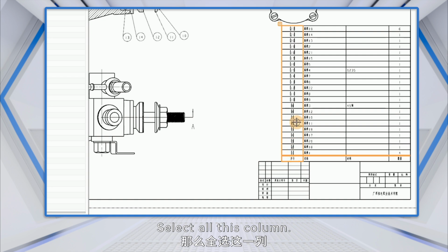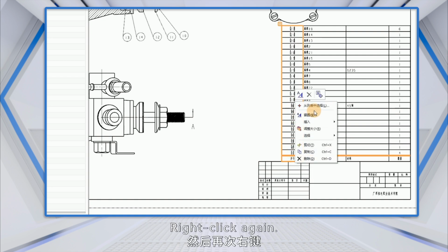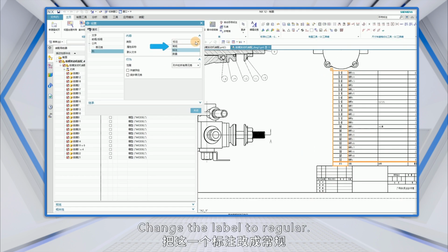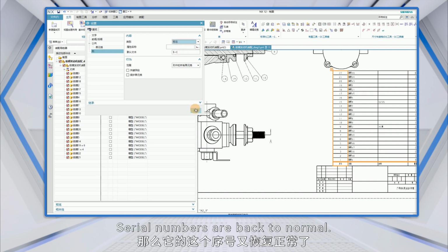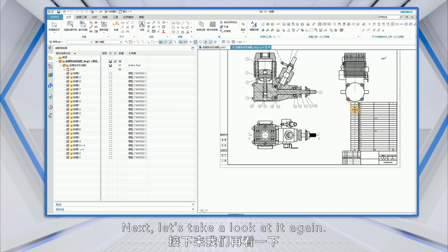Select all this column. Right-click to select a column. Right-click again. Click on Settings. Change the label to regular. The serial number is missing, and then change it to a label. Serial numbers are back to normal. Click Close.